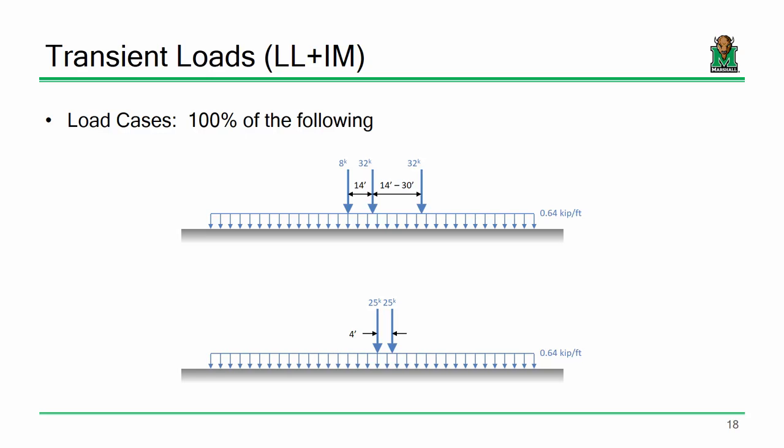So here's case 1 and 2. What's case 1? The truck and the lane. This 3-axle truck with the front axle being 8 kips, the 2 axles at the back being 32 kips. Variable axle spacing. We put the truck and the lane on the bridge and try to get the maximum force response we can. I'm being a little vague with that because we're going to talk about how you do that very specifically soon. All right. Bottom, the tandem in the lane.